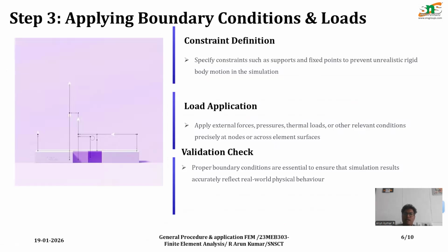Step 3 is applying the boundary conditions and loads. Constraint definitions specify constraints such as supports and fixed beams to prevent rigid body motions. Load applications simulate applying external forces, pressure, thermal loads, and other relevant conditions, precisely at nodes or across surfaces, while checking that proper boundary conditions are established, ensuring the simulation results accurately reflect real-world physical behavior.